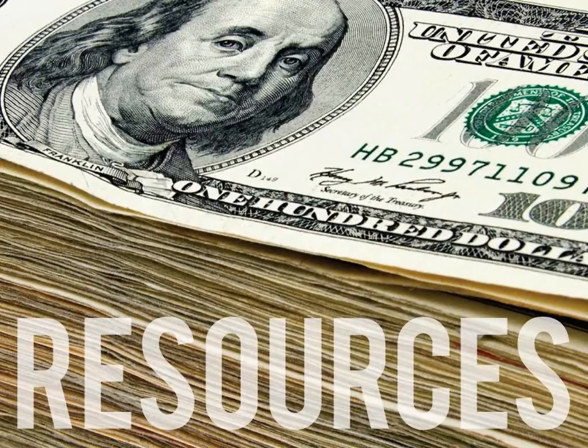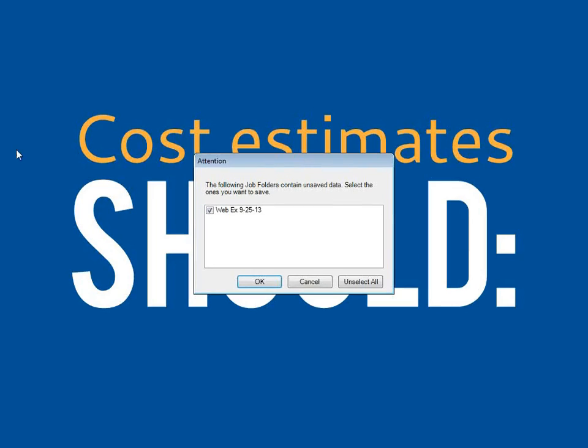For example, to put in the piling work, we might ask ourselves, what kind of crew would be involved with that? We'd have certain types of labor that we'd want to be using. What equipment will we use to do the piling work? And there's a dollar amount for each one of labor, equipment, or materials. As we start to build the project, those resources are going to have rates associated with them, and it's the totaling up of the cost that builds your cost estimate.